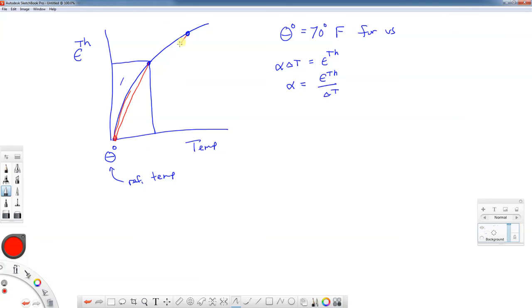If you're familiar with metals, there are two ways to define a slope in the nonlinear region. One is with the secant, one's with the tangent modulus. In some cases you may be given a tangent modulus and you need to convert this into a mean value. Okay, so what Abaqus needs is defined by the terms in red.